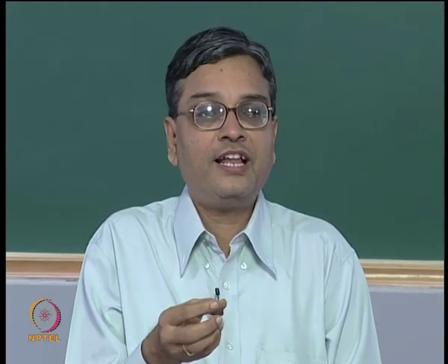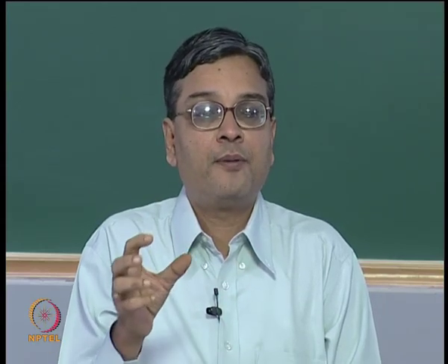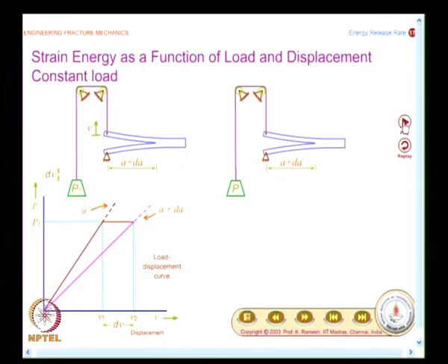You have already seen for the case of a spring, you have seen the load deflection graph, and area below the graph is the strain energy stored. Here again the loads are gradually applied. So, I can use the similar approach, and when I want to find out the difference, I will find out the final strain energy minus initial strain energy. We will look at now. So, what is the change in strain energy is what we want to look at.